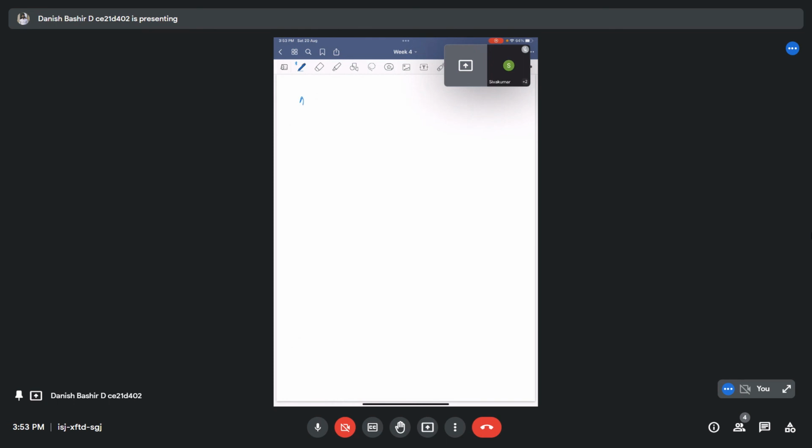So we got ASC equal to 869 mm square, and equating again as n pi by 4 d square is equal to 869 mm square. Let us choose n as 2. When we plug in this here, we will get d equal to under root 869 divided by 0.785, where 0.785 is actually pi by 4 into n equal to 2. D will be equal to 23.5 mm.